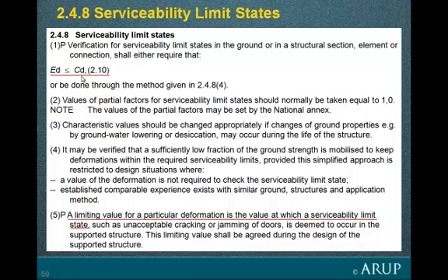On the other hand, that approach is given out here. A limiting value for a particular deformation is the value which is the serviceability limit state. It could be acceptable cracking or something like that. So that would give you a value of Cd, clearly a value to be discussed with structural designers, and not really a value that can be specified by the code itself, limiting settlement and deformation. For serviceability design, all the partial factors, in theory they are all there, but their values are unity. Generally, the National Annex could decide not to use unity, but in general that's always done.